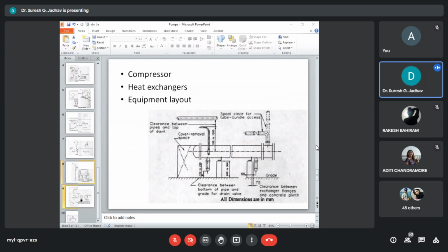Outline the clearance and working space in front and around both ends of the exchanger to facilitate shell cover and tube bundle removal as well as maintenance and cleaning. The channel end shall face the roadside for convenience of tube removal and the shell cover the rack side.